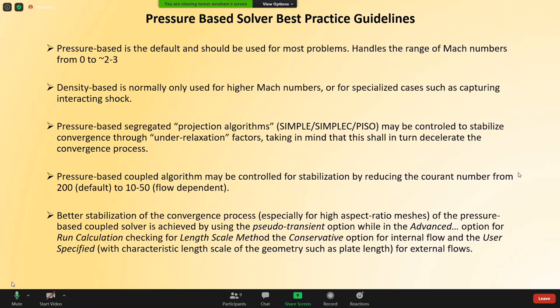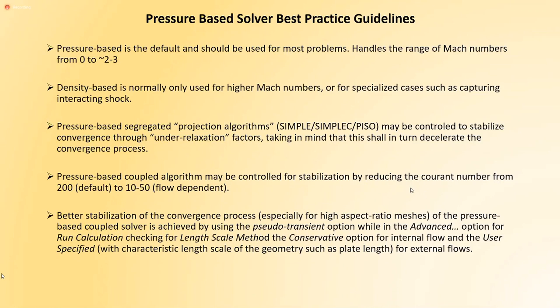It has a time scale. For a long time I preferred to work with the Courant, but it doesn't matter. It serves the same as the under relaxation factors. Better stabilization of the pressure-based solver can be achieved by pseudo-transient option, of course.